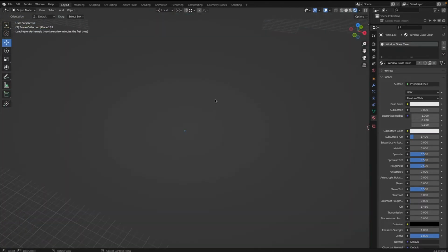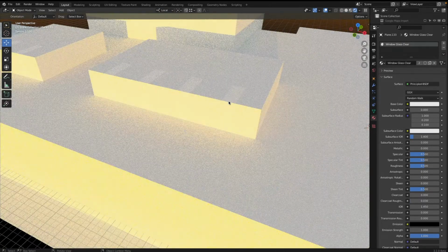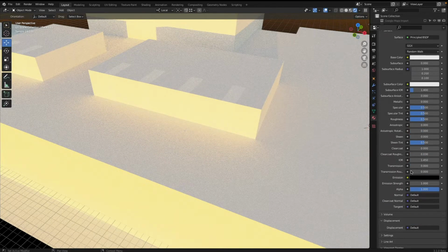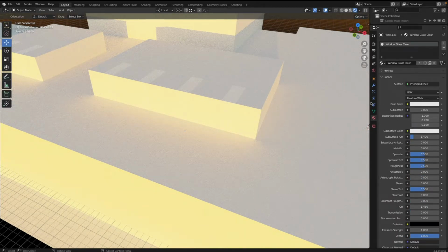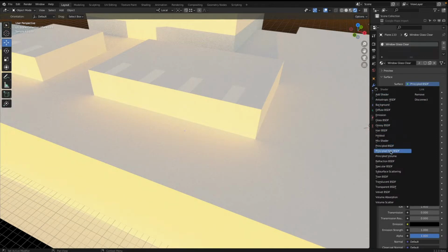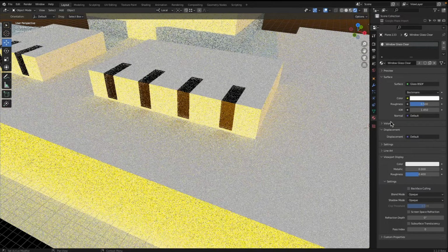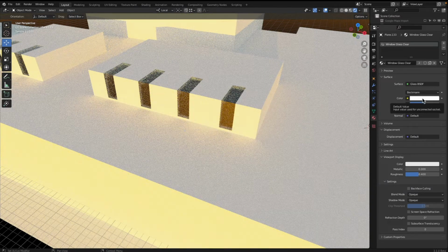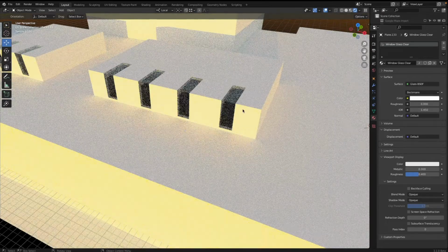So the material, let's go to here, Z and render. There we see, well, there's something, but it's solid. We want this to be transparent. The easiest way to turn this material into glass is we click here, and instead of being this Principled BSDF, which is called kind of like an Uber material, it can be changed into metal, stone, whatever, we would like this just to be glass. There we are. Then color transparency. White is clear. This is actually rough, so you see this is kind of blurry. Let's change this to 0 and then it's clear.